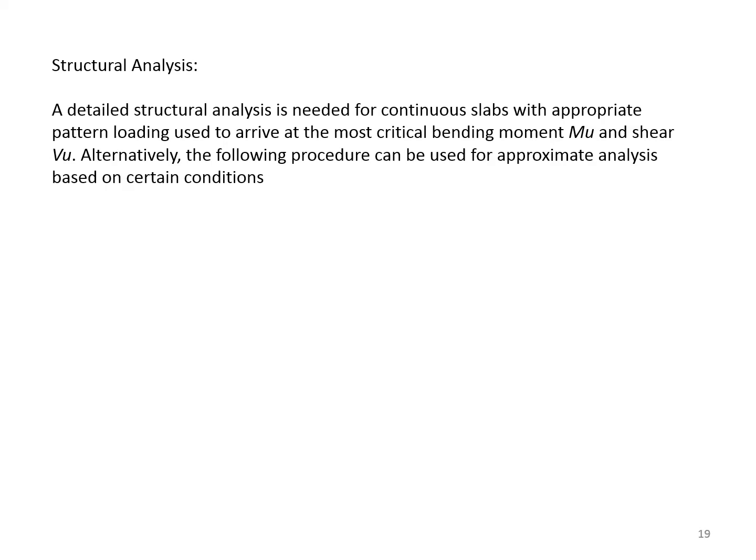Structural analysis. A detailed structural analysis is needed for continuous slabs with appropriate pattern loading used to arrive at the most critical bending moment Mu and shear Vu. Alternatively, the following procedure can be used for approximate analysis based on certain conditions.